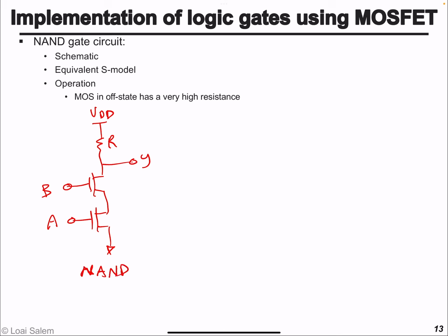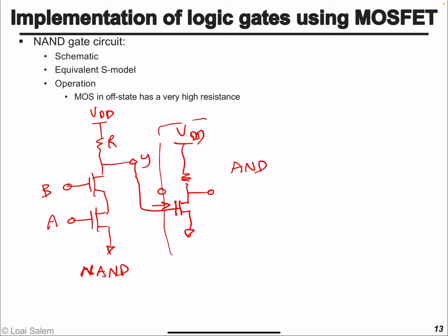and a resistor. Now, if I want to implement an AND function, well, just cascade or connect this gate to an inverter, the inverter that we just built. The good thing is the input is a transistor gate, current is equal to 0, and this allows us to cascade multiple gates. So we cascade an inverter to the NAND gate, so the output is going to be essentially the ANDing of A with B at this node.